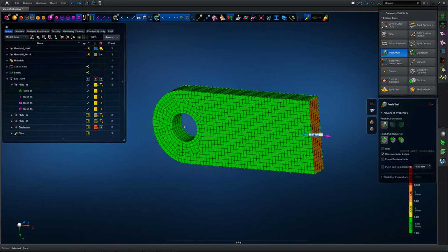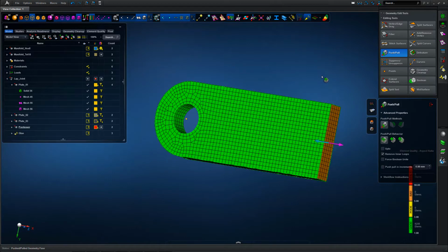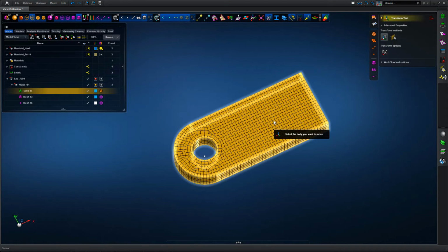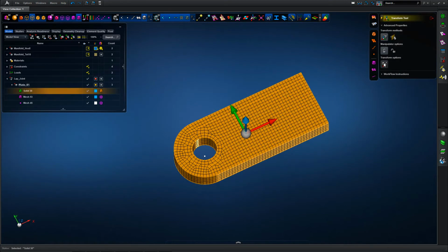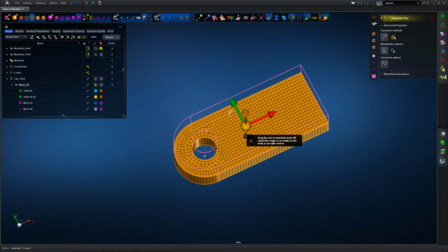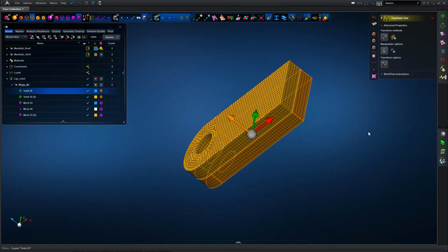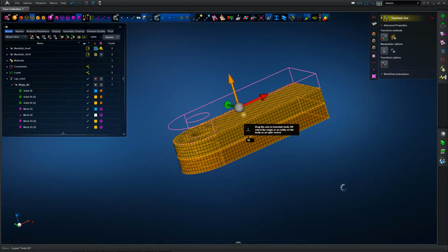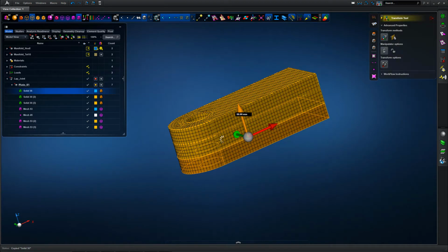Again, using the direct modeling geometry engine, we can push-pull the geometry with a live update in terms of the remesh and the element quality, so very quick to modify and amend the geometry and the underlying mesh. Again, the double lap shear joint is what we're going to be analysing or developing first of all. Using the transform tools in Apex, we copy the entity solid geometry with mesh up a couple of times to give us three discrete plates.